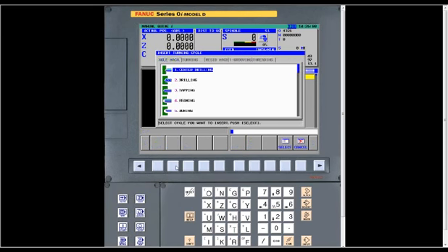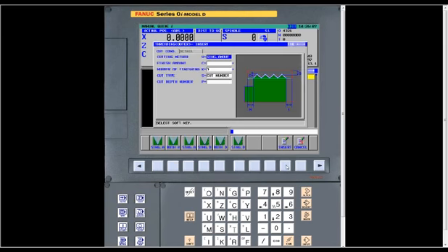We go back, we've done our grooving, now threading. Again, threading is very simple. Fill in the blanks again. We select threading, outer. The cutting method is just how it is feeding the tool into the thread itself. It defaults to single amount. That's like on an engine lathe when you've got your compound set up on 30 degrees, and as you go in deeper into the thread, it's only cutting on the leading edge of the insert. That's what it defaults to. But you've got six different ways of feeding into it.